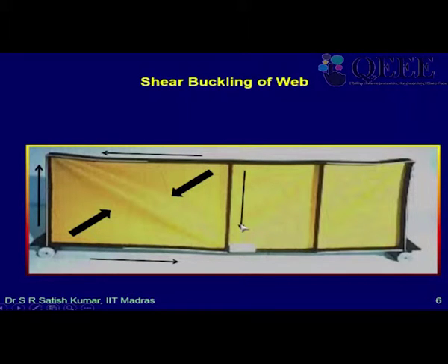So we have, let's say, a clockwise shear in every vertical section of the web. Now, whenever you have a shear like this on a rectangular element, these two forces are not collinear. There is a gap between them. So this web, as a rigid body, will try to rotate, right? So to avoid that, complementary shear sets in.